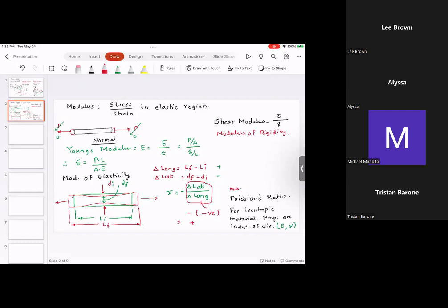And if you look at fluid mechanics, and if you study the properties of fluids or properties of liquids, especially for the liquids, there is a concept called the bulk modulus. Bulk modulus is volumetric stress. What is volumetric stress on liquids? It is pressure divided by the volumetric strain.